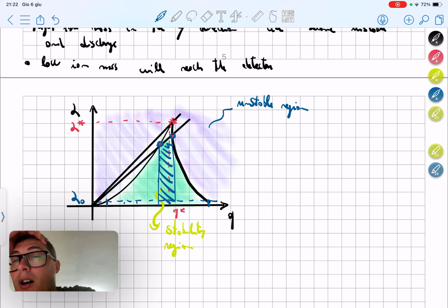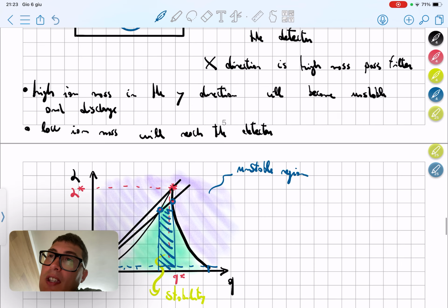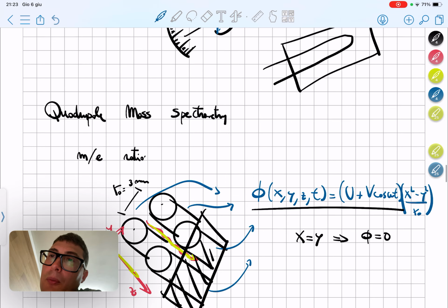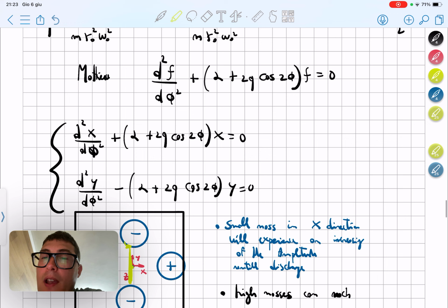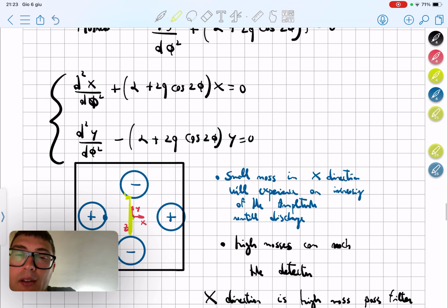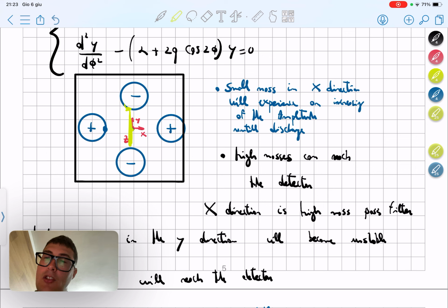We've seen a set of different types of pumps, some of which work well in a specific pressure range, some others work well in another range, and eventually we've seen a technique which is quadrupole mass spectrometry, which is used to determine what type of gases are still inside the chamber by ionizing them and making them pass through this quadrupole detector, which according to their specific mass to charge ratio lets us understand what type of ion was inside.